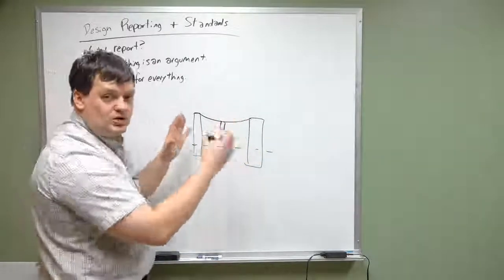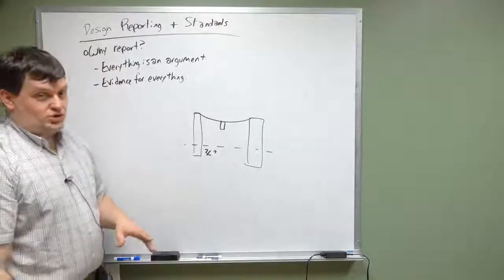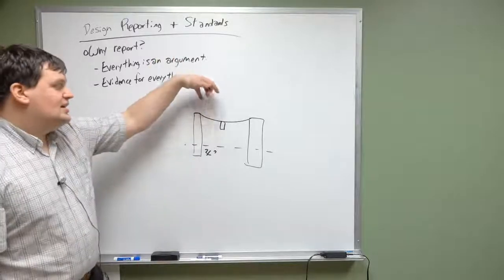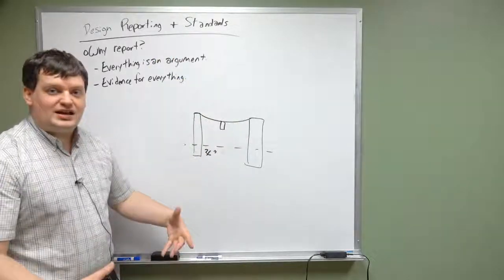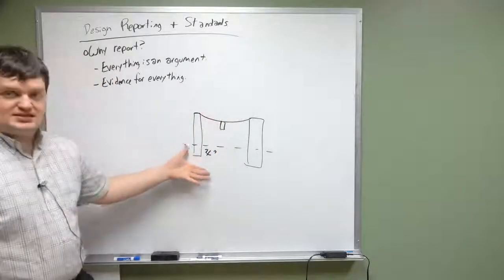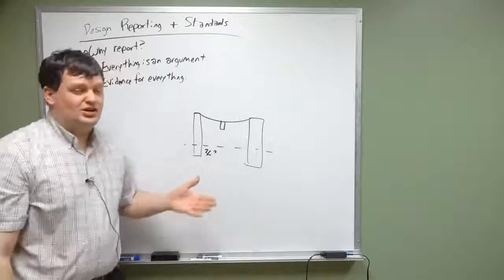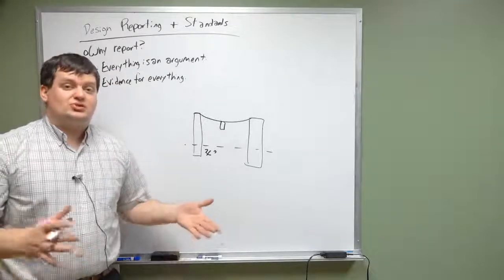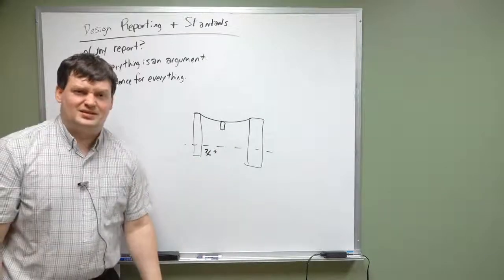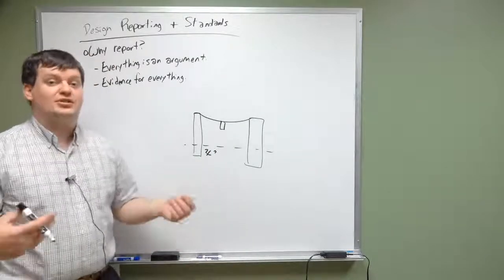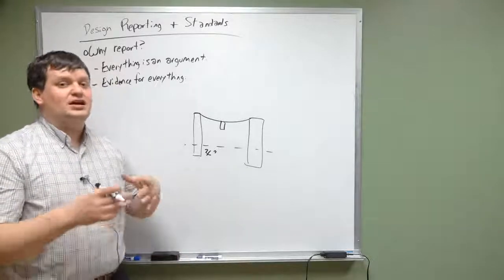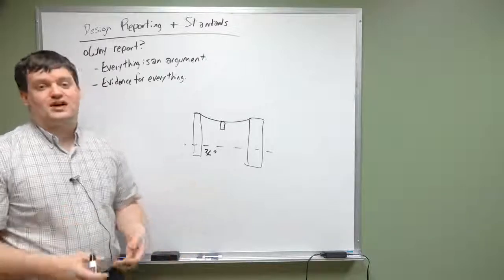Do you know that this is going to be able to withstand a hurricane? Do you know that it's going to be able to withstand the weather? Is it going to be able to withstand an ice storm? If this thing experiences ice along the top of it and gathers a significant amount of ice, is that going to cause these posts to rotate in the soil? Is this depth too much? All of those questions you should be able to justify. And this is a very simple system. It's two sticks and a rope with a light. But you should be able to justify everything about it. And the design process reporting is necessary to get to the point where you can justify your decisions.